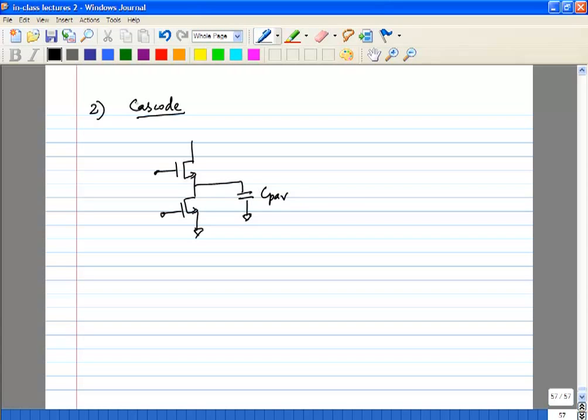And the other thing: what would you do with the gate of the cascode? Typically you would connect it to VDD in most of these cases. That's not a problem. You want to get maximum headroom for the main amplifier. Okay, so finally,